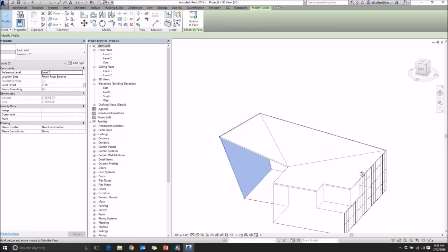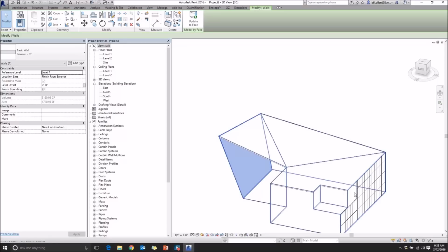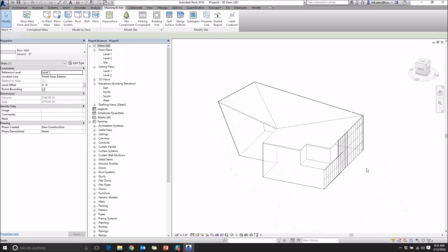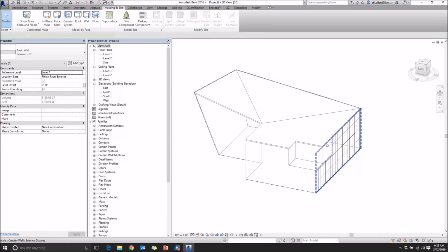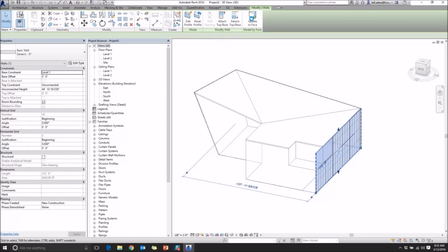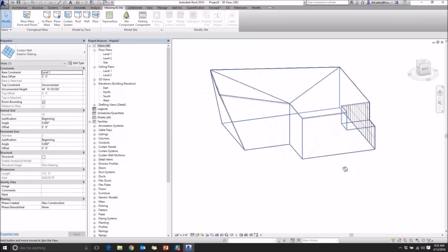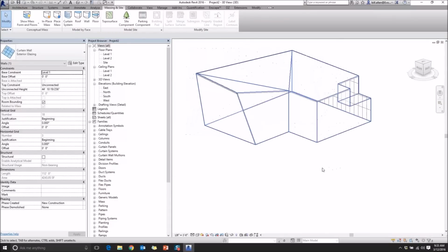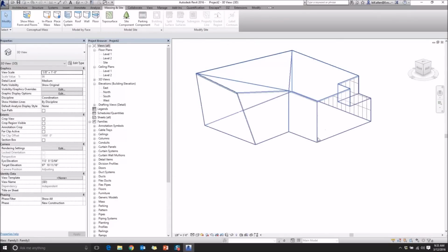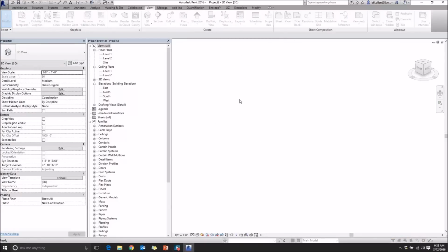And over here, you can see that this geometry, now I'm getting the option. I'm not totally having to remodel all of this. All I'm saying is, as long as that face is still there, it just updated. I can say update to face, and it's automatically basically recalibrating that face, that surface, to host to that same location, which is pretty cool. Alright, so that's how you can start creating real Revit systems from the conceptual mass. Create a new one, conceptual mass.